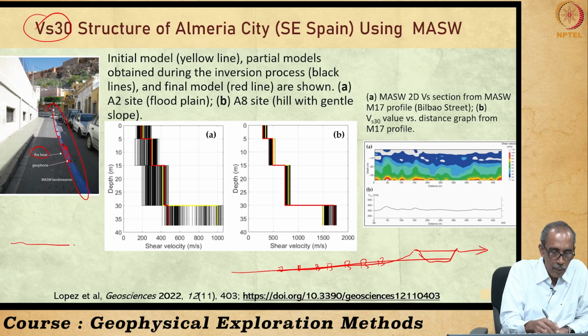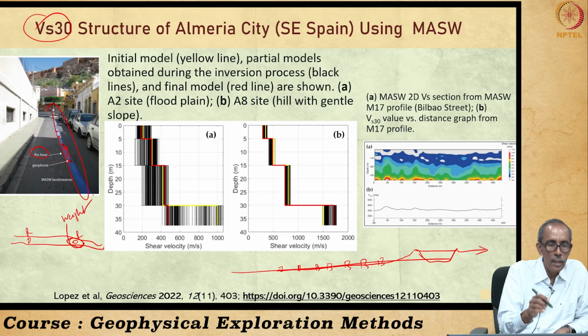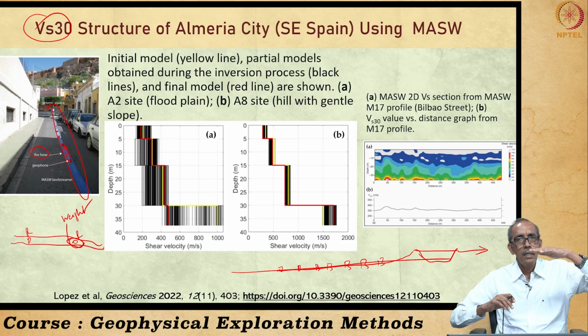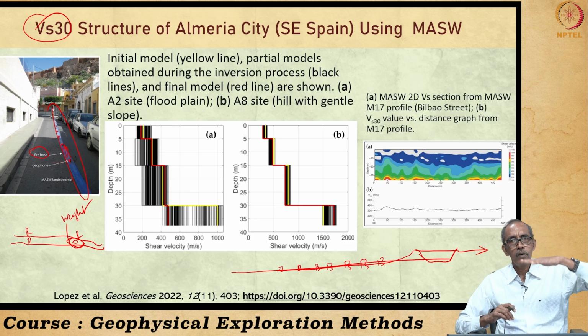That means this is the hose pipe, to which we have attached a geophone receiver and the next receiver. Around this we may add some weight, right. Weight may be in the form of maybe a steel plate, right. It can be maybe a steel chain kept around that, so that the hose pipe, the geophone firmly touches the ground surface, that is the aim, right.